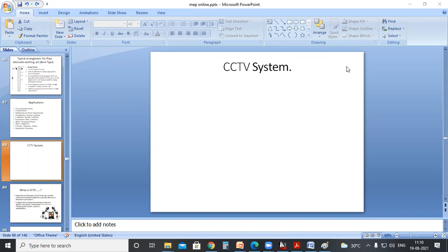area. If there is a generator, you have to put it under surveillance. If there is an entry or exit point, you have to monitor the entry or exit point. If a person can cross the compound wall, you need to cover all the area. There should be no blind spot, providing the CCTV drawing. I can just show a drawing that we have provided for a client. Based on that we can discuss.